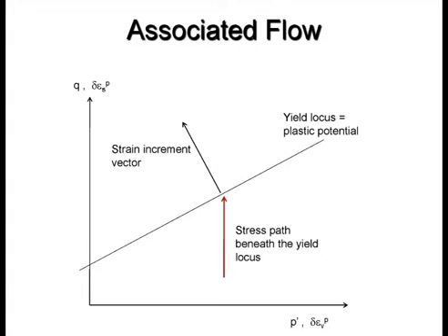It's a straight line in this direction. So what we do is, we say this is also the plastic potential. This is what we mean by associated flow. Alright? Associated flow. Now, what is the consequence of this? How do we apply this? It provides a very simple vehicle for us to examine how plastic flow occurs, how the flow rule directs the